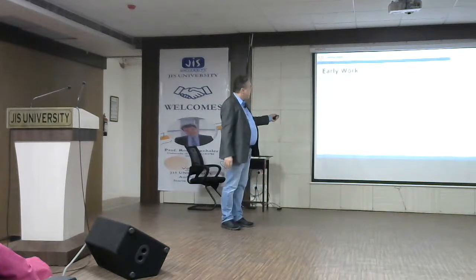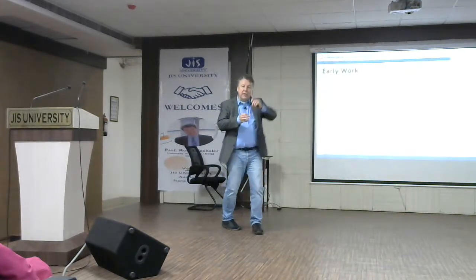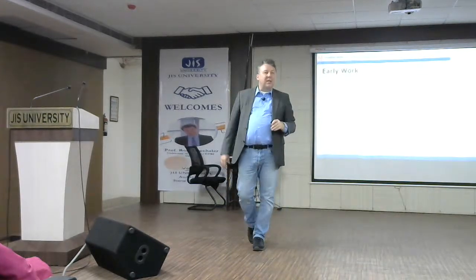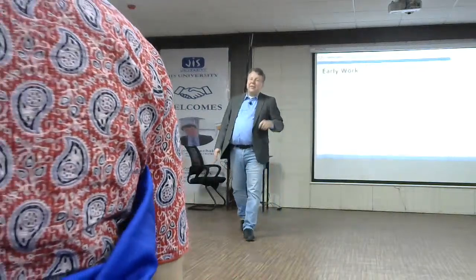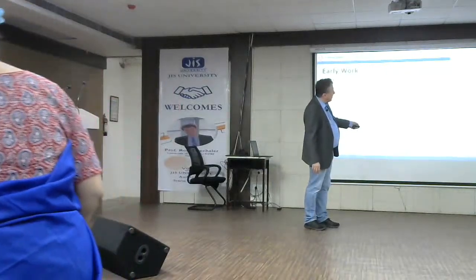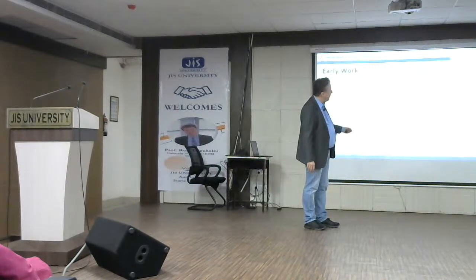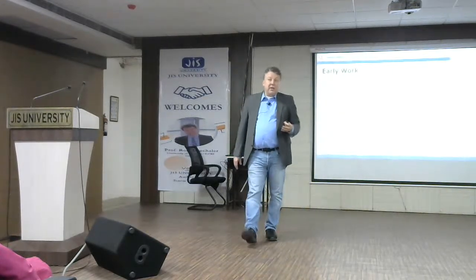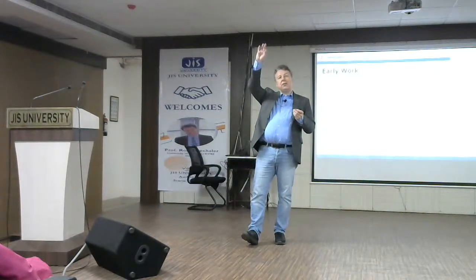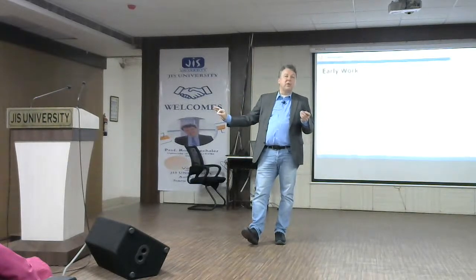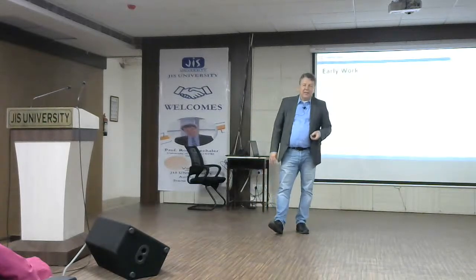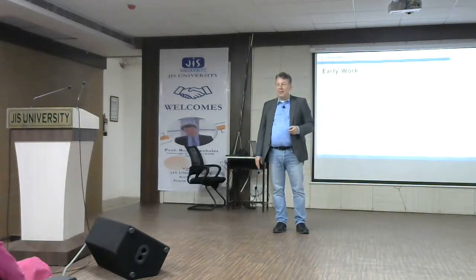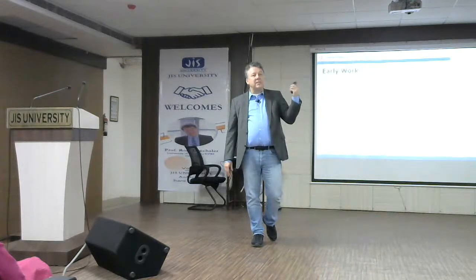Already in very early years, people observed that this kind of peak reduction, the memory peak that you need during the construction, is somehow the bottleneck of these approaches. That's a picture that I took from a paper from 96, so quite some years back. Already there, people saw that sometimes representing a function in terms of memory, here for a specific data structure called BDDs, at the output it's small, but in between it is large. And that's very typical for these techniques, that you sometimes need a lot of memory consumption, and then at the end, it becomes smaller again. That's what we studied in my team for the last 20, 30 years. In the meantime, we have a very good understanding of where this comes from. And that's exactly what I wanted to show you with some examples, so that you understand what verification is in general and how these techniques work these days.